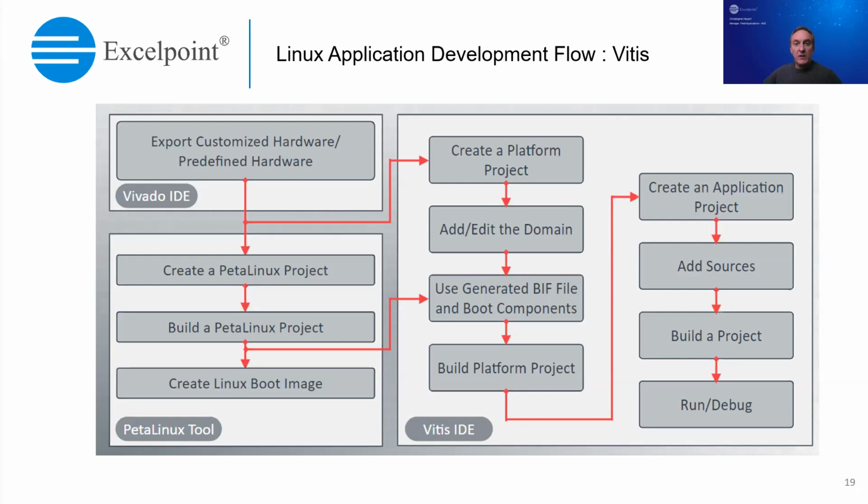Petalinux is then used to develop and build the Linux-based project using the petalinux-create, petalinux-build, etc. commands that we've been discussing up until now, which then generates the device tree blob, the first stage bootloader, U-boot application, a Linux kernel, root file system, and all the components, as well as user applications where they're available already. Then the Vitis IDE can be used to develop Linux applications. You only need to specify a Linux domain, and it can then begin building Linux applications from the templates available.